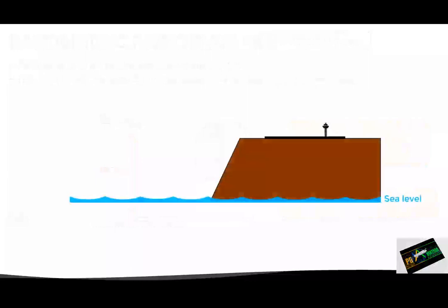Suppose that under certain conditions the pressure at sea level is 29.72 inches of mercury, so in other words this would be our QNH, since as we saw in the previous video, the QNH is the pressure level that identifies the mean sea level. This means that if the pilot adjusts the altimeter with 29.72 as the barometric reference, it will measure the altitude in relation to mean sea level.